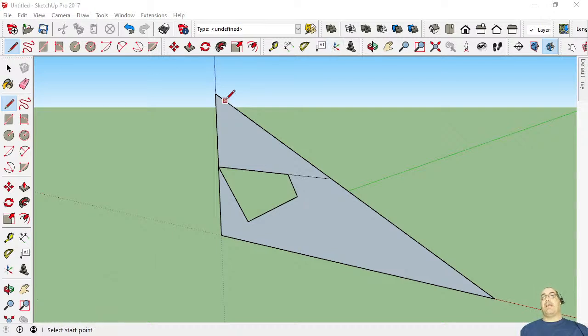connections exactly parallel and exactly at 90 degrees, then when you come to do extrudes and things like that, you often will see that SketchUp will put extra lines in so that it can mould the shape of something to fit. So it quite often can be a good exercise when you first load a model in and do your first extrude to go around and check your angles and check all these lines and see if you can remove them.